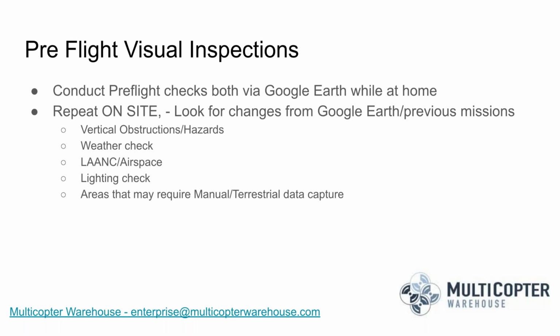On the iOS version, there is an image capture mode, and you have the option between safe and fast. Those 2 names don't really spell out what's happening. In the safe mode, the software actually uploads each individual waypoint where each photo will be captured, and the drone will fly to that waypoint, stop, hover, take a photo, then fly to the next waypoint, stop, hover, photo. And so that's the safe mode.